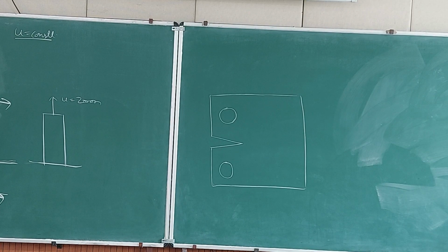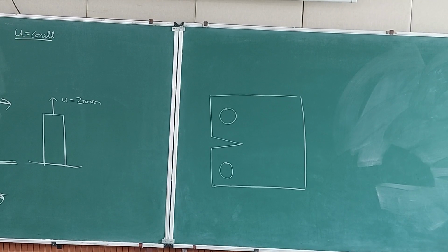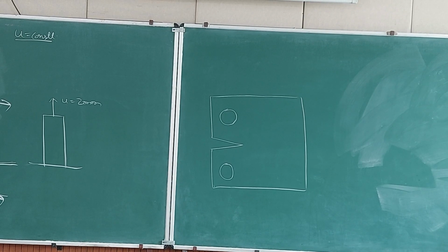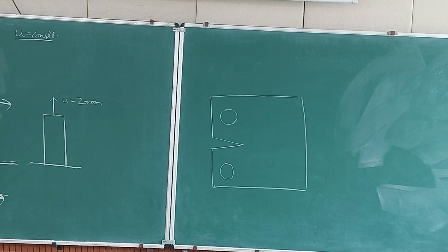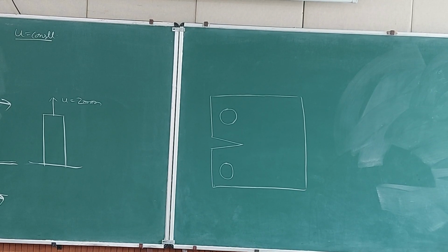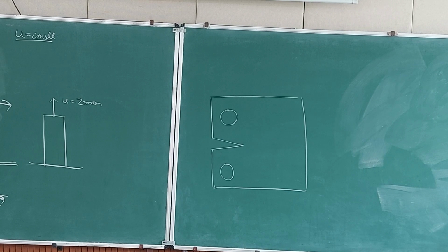then what should we do? Should we do a force constant test or a displacement constant test? So force, stress cannot be constant in a cracked sample. That we cannot achieve ever, okay, because there is a crack. So what should we do? Should we do force constant or displacement constant? If you have both of the options, which one will you do and why?